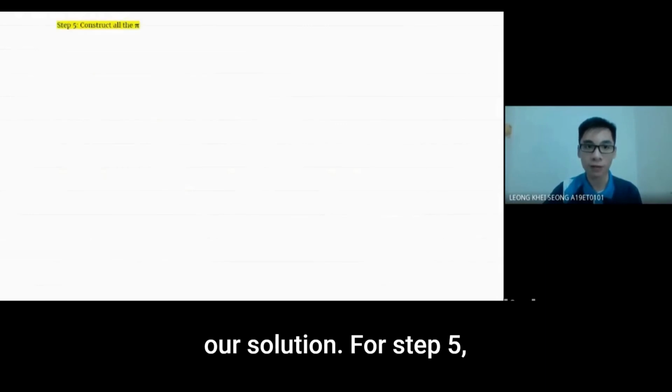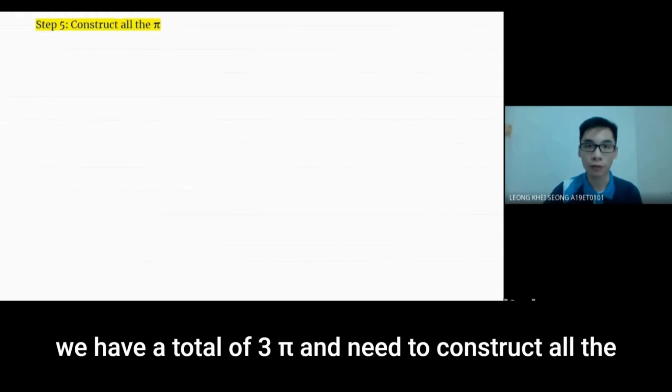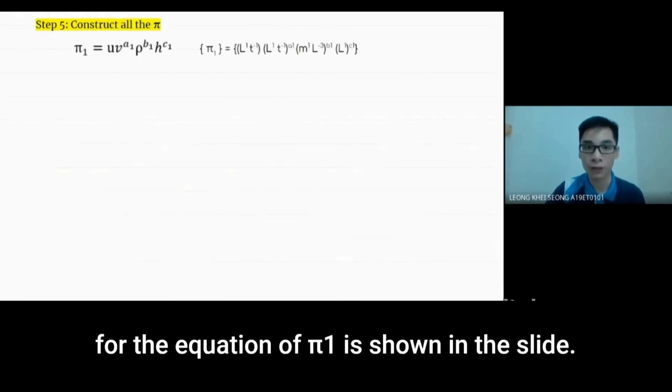For step 5, we need to construct all the pi's. Since for this problem we have a total of 3 pi's, we need to construct pi 1, pi 2, and pi 3. For pi 1, which is equal to u V to the power of a1, rho to the power of b1, and h to the power of c1. And the primary dimension for the equation of pi 1 is shown in the slide.